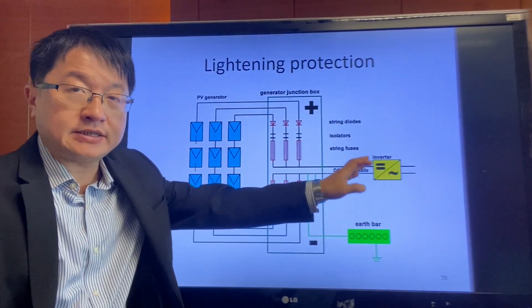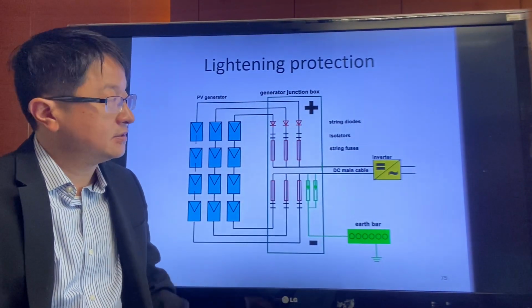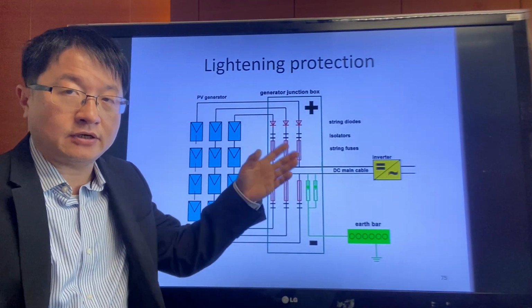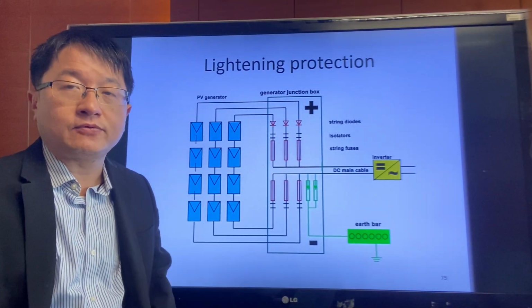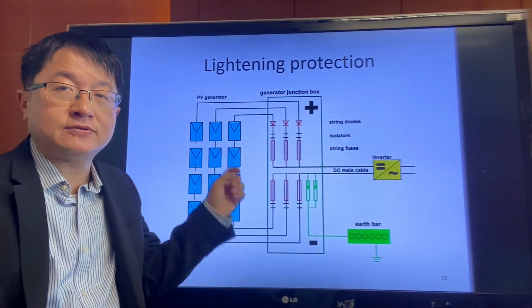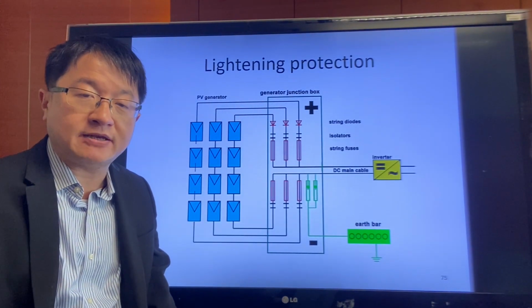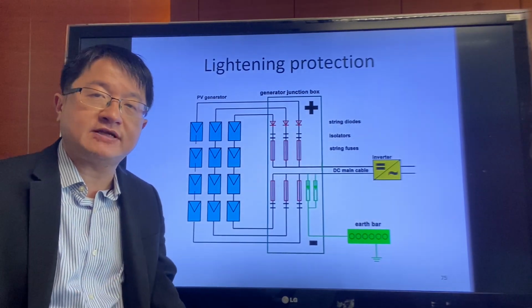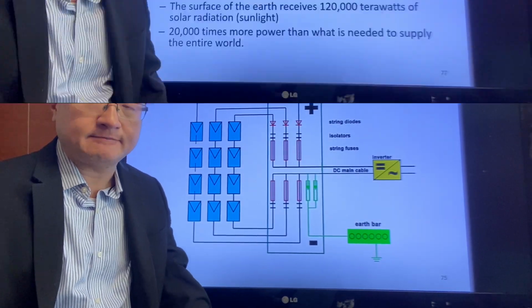Because if we connect it to any switching device, this switching turn on and off will create a back EMF, and this back EMF may then pass back to the PV panel and damage the panel. So all these safety measures have to be in place.